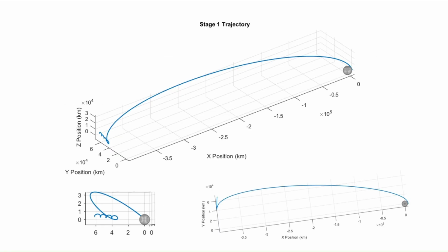So this is what the trajectory looked like for stage 1. Stage 1 being getting to the Earth's atmosphere. You can see here you're orbiting the moon, and then once the engines burn, it shoots up out of the plane and it comes in just barely not tangential with Earth's atmosphere. I decided to change it to be not in the ecliptic plane or almost the ecliptic plane because the moon is not in it either, because the velocity ended up being not quite enough. So having it out of line like this means that less of it is canceled out by the moon's velocity.